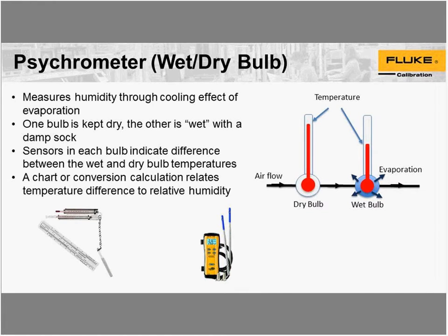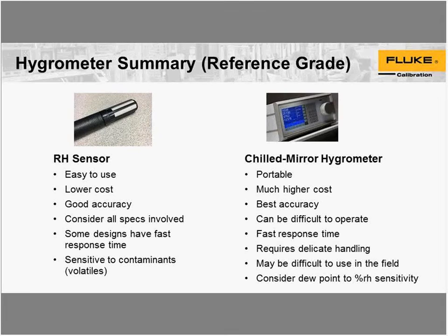So really quick, the hygrometers are either the relative humidity sensor, which is the capacitive or resistive type, or the two-mirror hygrometer. Again, there are a lot of other methods of measuring humidity otherwise, but these are the most common. And then here are side-by-side comparisons between them. Some rate sensor is the speed at which they measure.